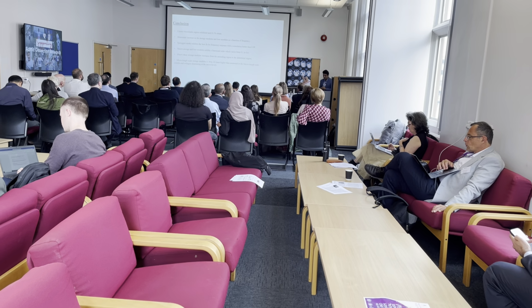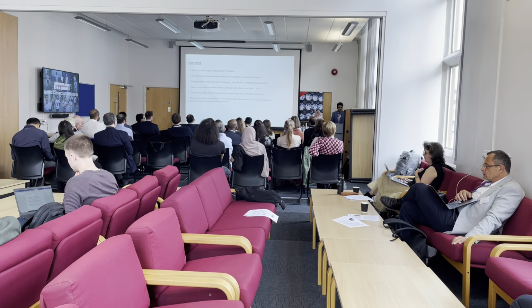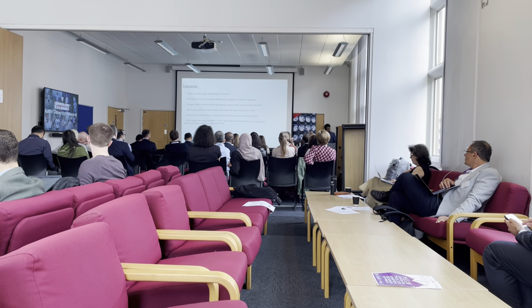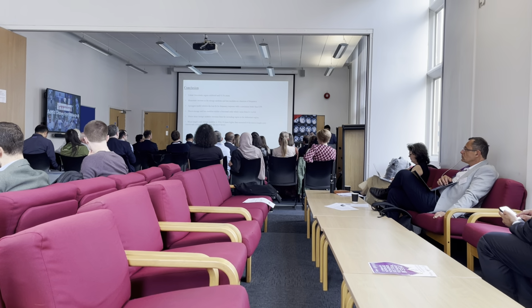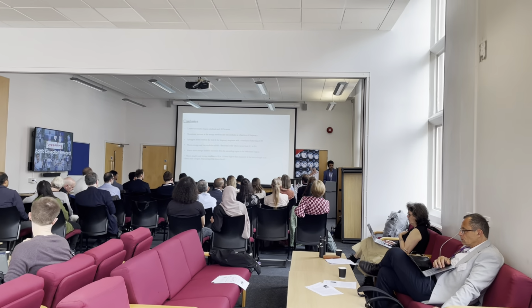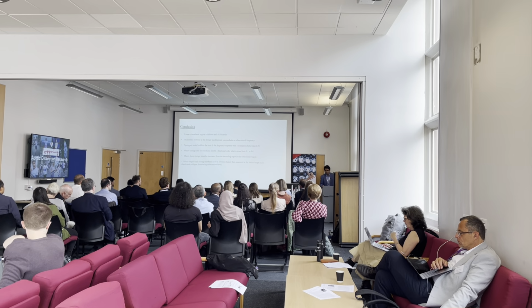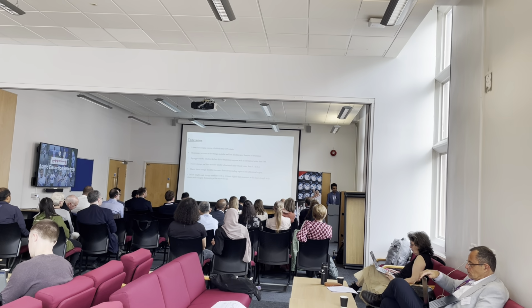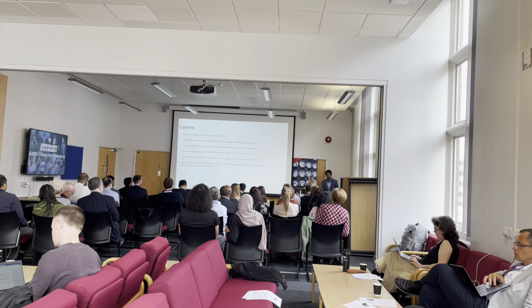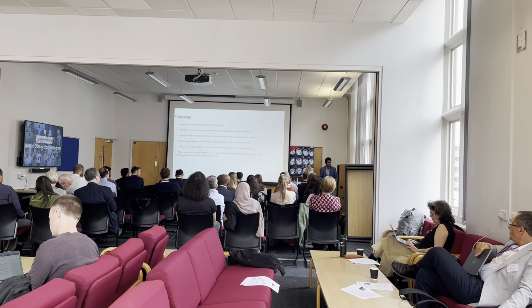So in conclusion, one of them was that we were able to quantify the properties at both the micro length scale and the macro length scale. I was able to extract the linear viscoelastic region up to 0.1% shear strain. There was a monotonic increase in the storage modulus and loss modulus as a function of frequency, which implies that there was a power law behavior across different regions of the aorta.